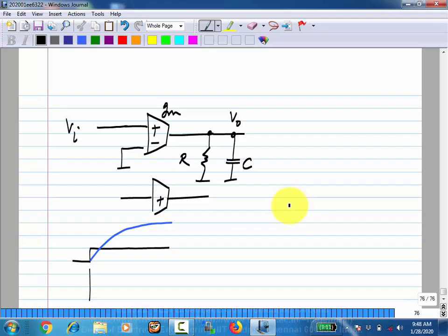So now if I want to detect smaller and smaller signals, what do I have to do? I have to increase the gain. So how do I do that? Increase the GM. But let's say I put n times GM here, this also becomes n times C. So what happens then?